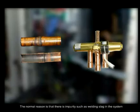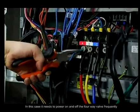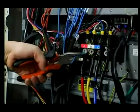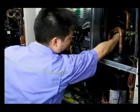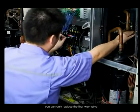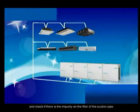The normal reason is that there is impurity, such as welding slag, in the system, and the impurity blocks the valve or slide. In this case, you need to power the four-way valve on and off frequently and hit the four-way valve several times with rubber objects when the system is running, so that the slide block can be moved by the refrigerant's momentum. If the malfunction cannot be solved, you can only replace the four-way valve and check if there is impurity on the filter of the suction pipe.